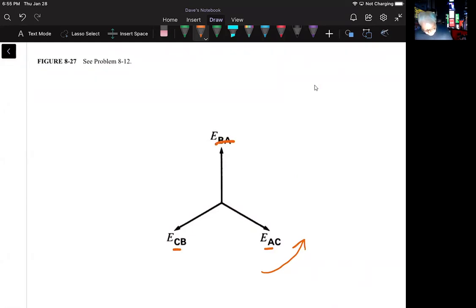All right, we could reverse it by changing any two of the conductors. All this may appear to be a trivial change. It can be a major problem when large bus bars or high voltage transmission lines have to be interchanged. In practice, measures are taken so that drastic mechanical changes do not have to be made at the last minute. The phase sequence of all major distribution systems is known in advance, and future connections are planned accordingly.